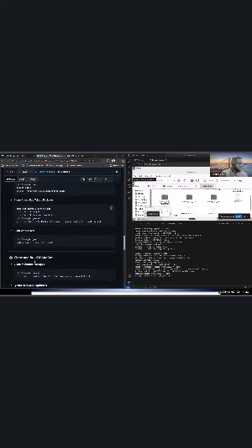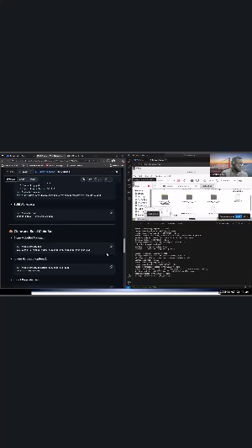So we've been able to clone the package, and we're able to build. Now we're going to ignore some packages in the mobile package because they're for the hardware. So you're just going to add this touch, a COLCON_IGNORE file, right?